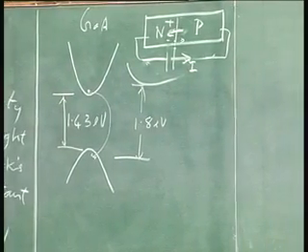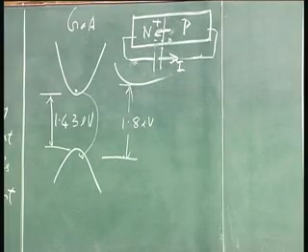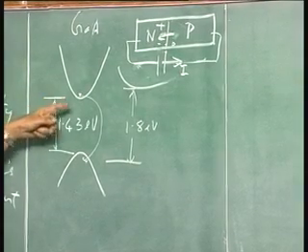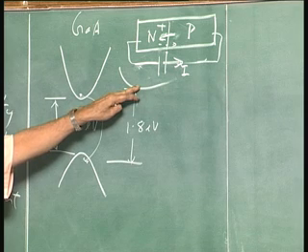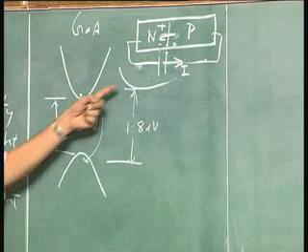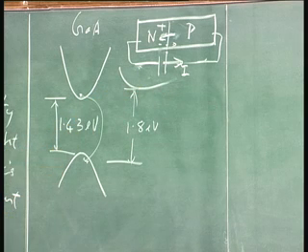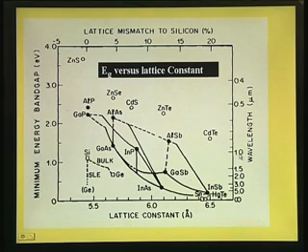Okay. So, let us see, this diagram that you have drawn is a diagram for gallium arsenide direct band gap, and also we have said the minimum band gap that is put there implies that this is the minimum compared to that. Okay. If you transfer the electrons from here to here, if they were there, then it would have been indirect transition. Okay. So, I am just trying to point out some of these things which are in this diagram. So, on this side you get that wavelength which is 1.24 divided by energy.